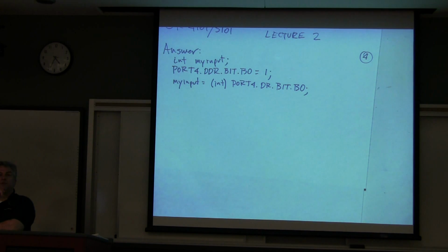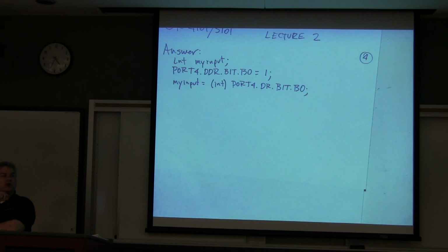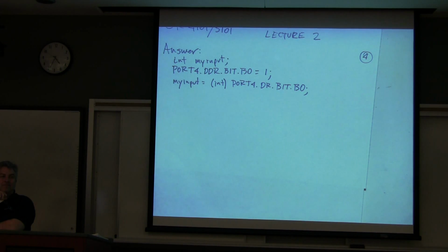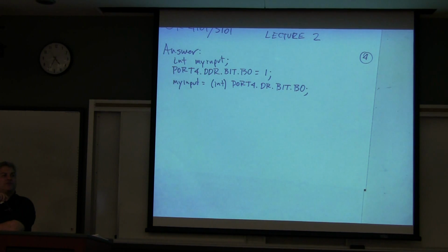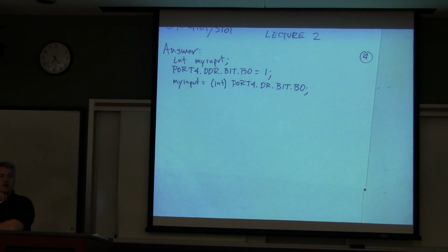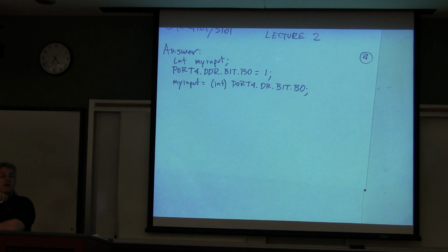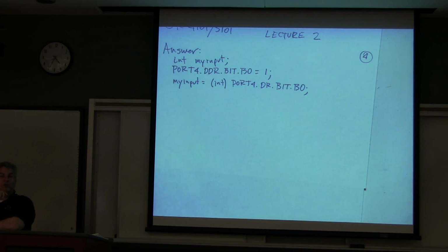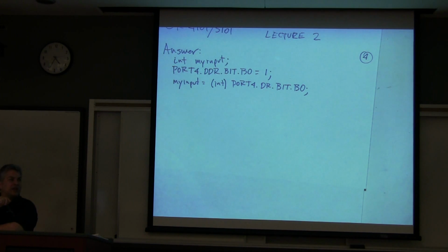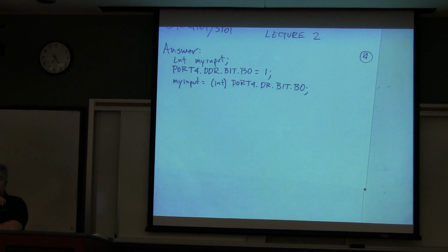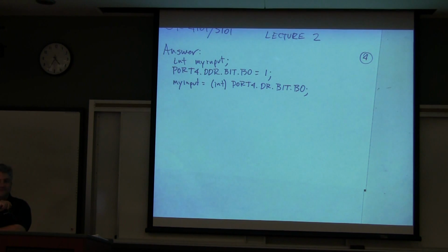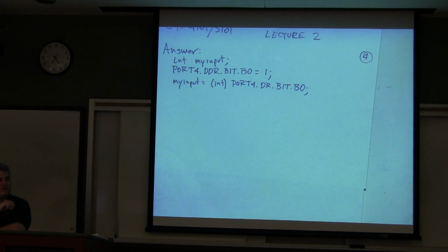Integer's what? How many bits? It depends. Integer is however many bits your compiler says it is. It all depends on the architecture of your device and how wide its word is. So, for example, we have a 32-bit machine, so I've got to check to make sure, but I believe for our 32-bit microcontroller, an integer will be 32 bits. In the old Renesas board, our word was 16 bits, and so an integer was 16 bits. All of this should have been taught to you in computer organization, right? You remember, dusting off the cobwebs? Just dust off those cobwebs, all right?